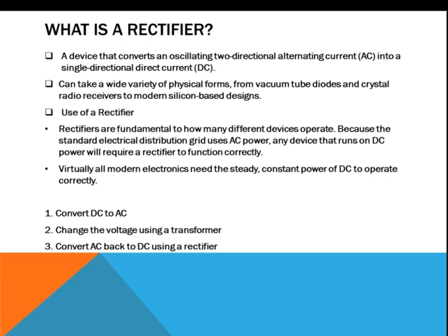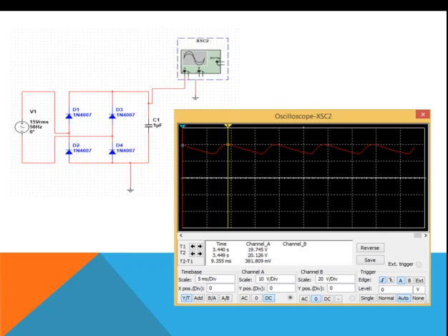For this project, I have done my part, which is the rectifier circuit. As we know, the bridge I have done manually. I just put the four diodes here and connect them to be like a bridge. Then we need to put a capacitor here in order to act as a filter.